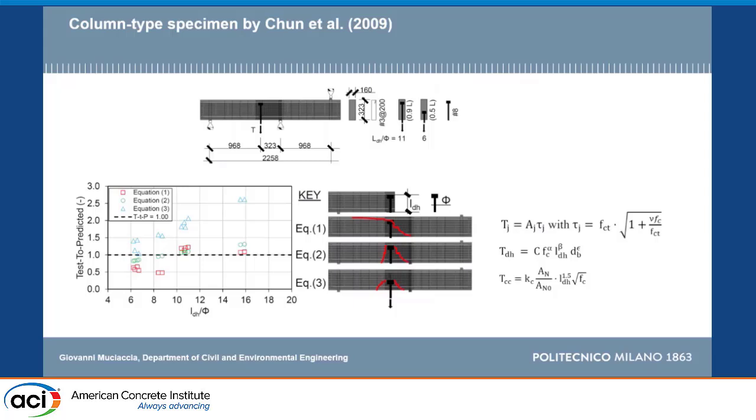Now, I am on purpose not reporting here the potential increment from the effect of bending moment, to see how far we are, in the sense of how big the factor accounting for the bending moment should be. Because if you make it simply analytically, this is almost square, and for an almost square portion, your increase is 1.5, so it's not very big. So the prediction is plotted without accounting for the potential effect of confinement.